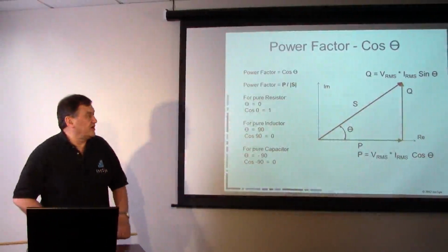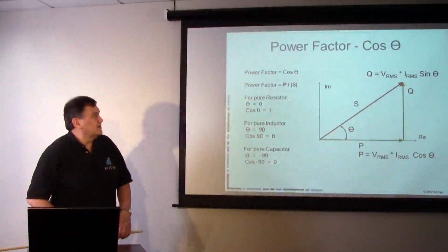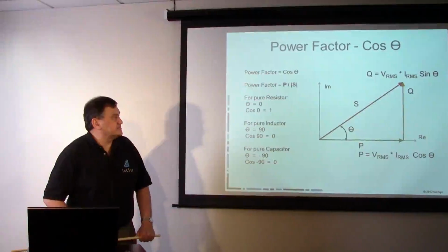Typically, you'll have loads where the power factor can be anywhere from 80% to 99%. That's just a shorthand way of talking about the relative proportions. We primarily apply power factor to loads. Power factor for loads in the summer is a lot lower. In the winter, where it's primarily heating, you can get very high power factors in the 98% range. As you get into summer conditions with lots of air conditioners, those power factors can drop to the 90 to 80% range.